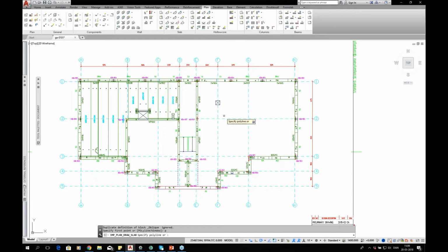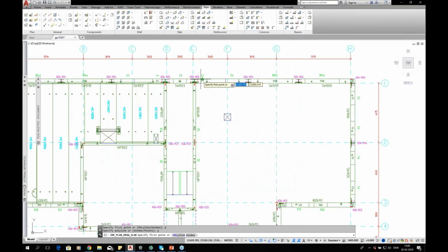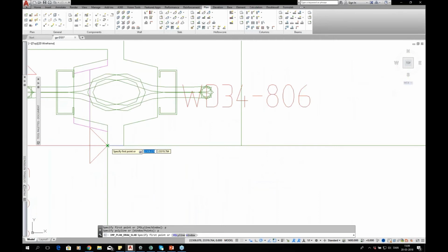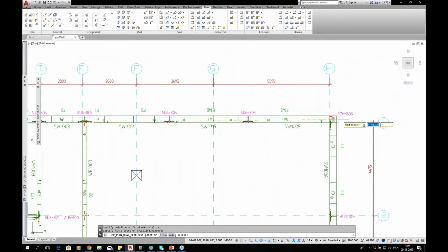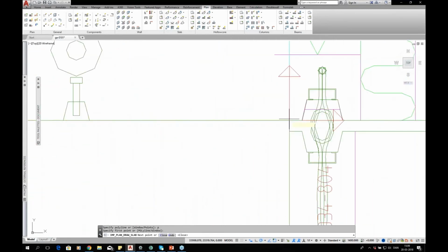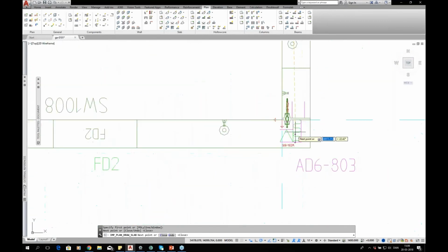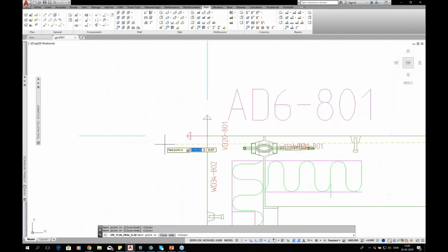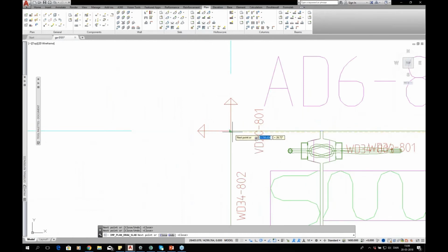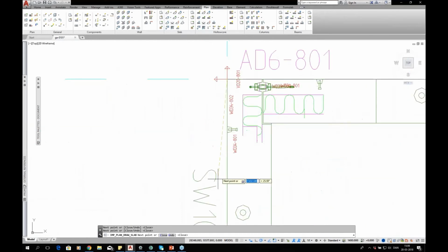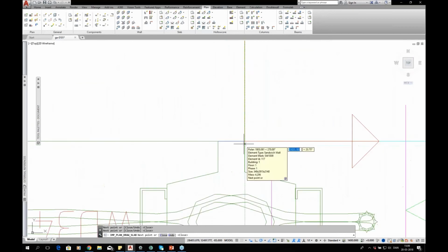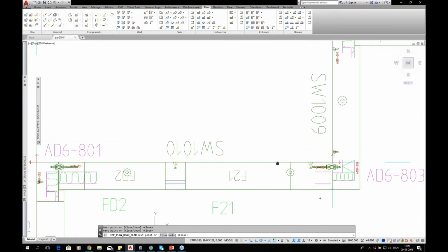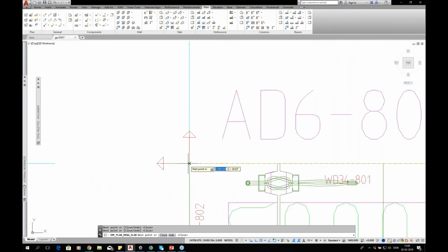So what I do again now is the same as what I did with the hollow cores. Pick a polyline or points. As I don't have a polyline here, I'm just picking points. But these, of course, have a span that's a little bit larger than the hollow cores. I have up to 12 meters here, I think. There we go. There.